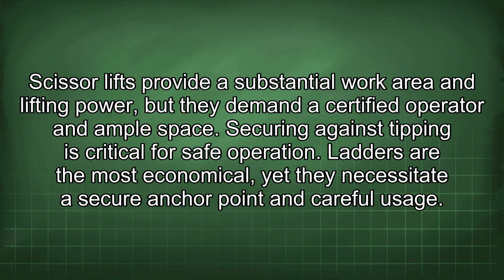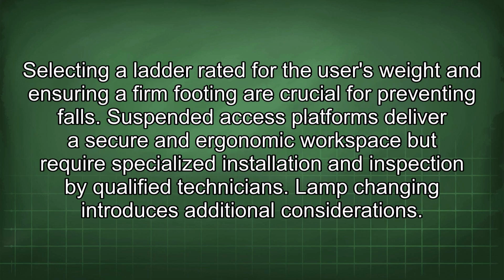Scissor lifts provide a substantial work area and lifting power, but they demand a certified operator and ample space. Securing against tipping is critical for safe operation. Ladders are the most economical, yet they necessitate a secure anchor point and careful usage. Selecting a ladder rated for the user's weight and ensuring a firm footing are crucial for preventing falls. Suspended access platforms deliver a secure and ergonomic workspace but require specialized installation and inspection by qualified technicians.